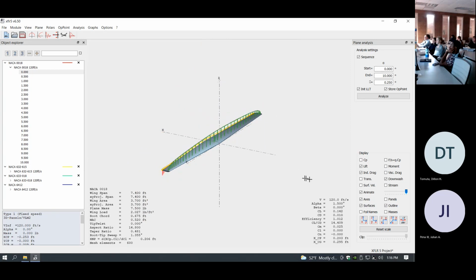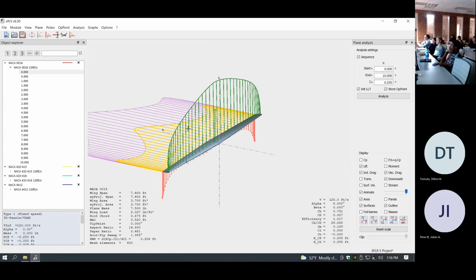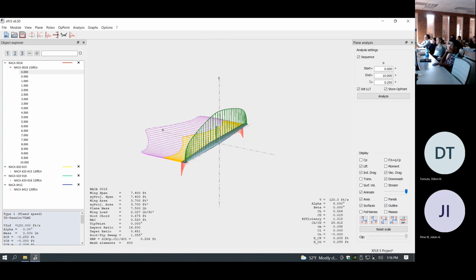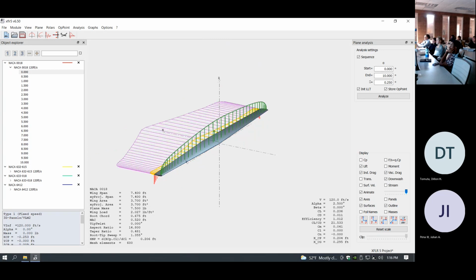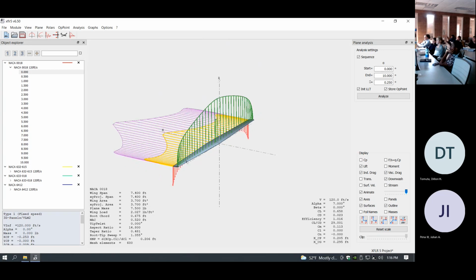Can you click on viscous drag too? Oh, yes, I can. Because viscous drag is essentially profile drag. Yeah, they're the same. Drag is what's set when you choose your cross section. However, the induced drag, as you pitch up and pitch down, you increase the lift. Of course, it is going to skyrocket. That's called induced drag.